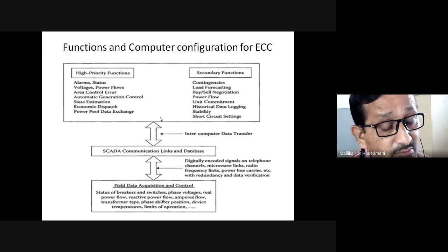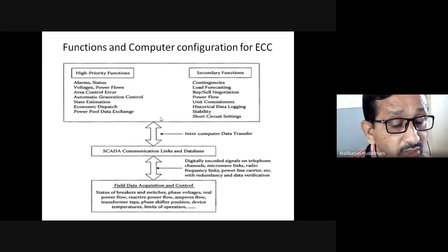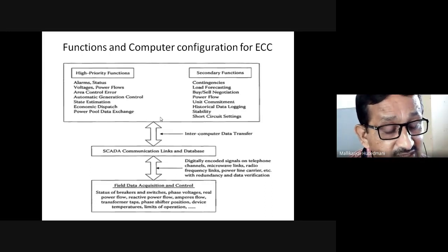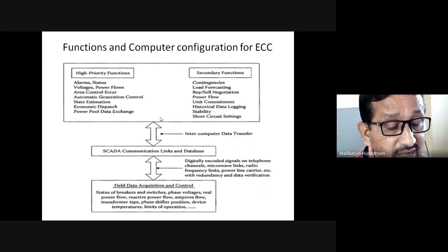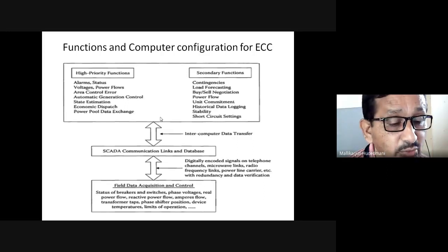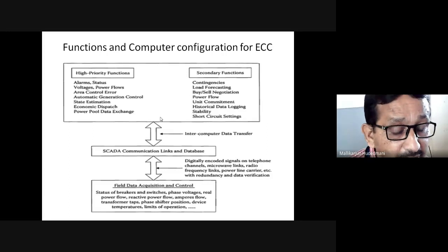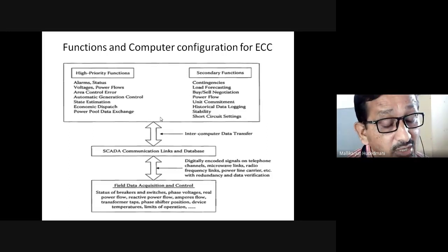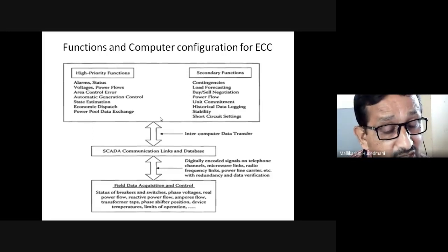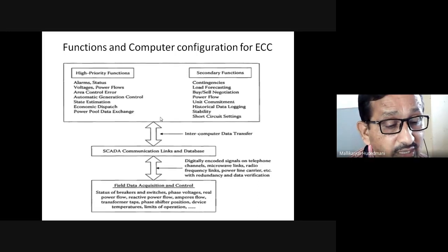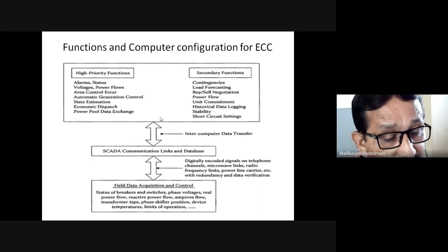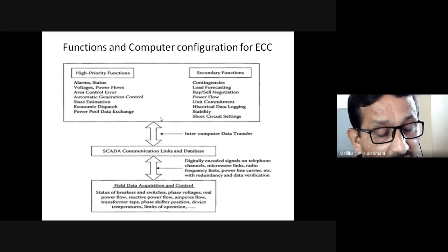If that error is not brought to zero, mismatch between P and mismatch between Q indicate that there are frequency oscillations and reactive power imbalance, or voltage instability due to reactive power, can be a situation. To address that, the error shall be kept under control relative to the requirement. So that is one of the important stimuli for the automatic generation control.